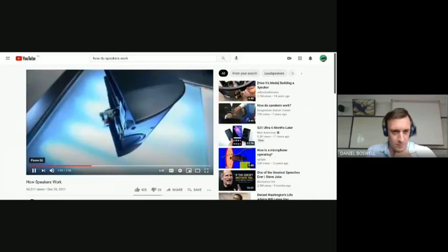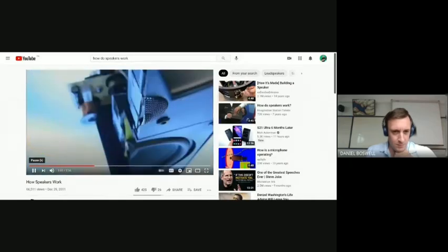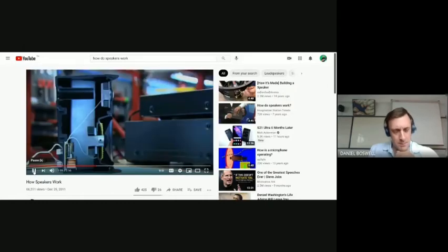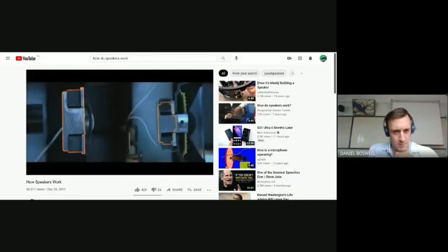In the enclosure are two speakers, one for low sounds and one for highs. Okay, so you've got your low sound at the bottom, which you could call a sub, and then a tweeter at the top. We'll look into this later. Both have the exact same parts and work the exact same way. A permanent magnet. Diaphragm, just a plastic membrane. Stuck to the membrane, a copper coil.